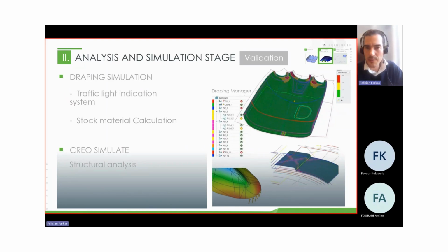So you can see some of them, the first ply, is no good to go. It has exceeded the shear angle, which does not support having that layer. So either we have to change the thickness of the material, or we have to change the angle, and we have to investigate that.